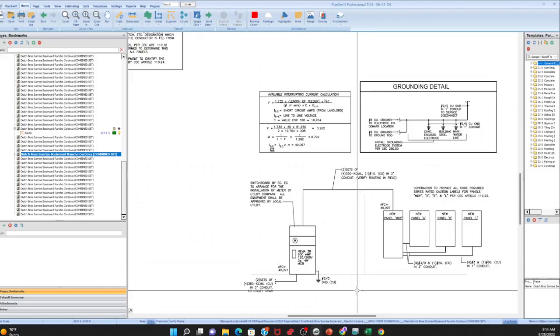Yeah. Well, now, if it's from the ground up, then you've got to find the site plan, because the site plan is going to show you. And don't use the civil set, right? The civil set has nothing to do with the specifics of electrical, even though the electrical is shown on the civil set. So you're always going to look at the E plans. If it's from the ground up, just like this one, the little Dutch Brothers, it's going to have a site plan, because it's going to show us where the utility transformer is. We just don't have the time to go through it on this one.